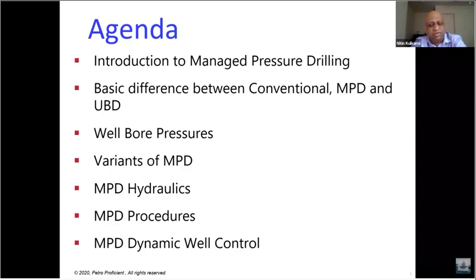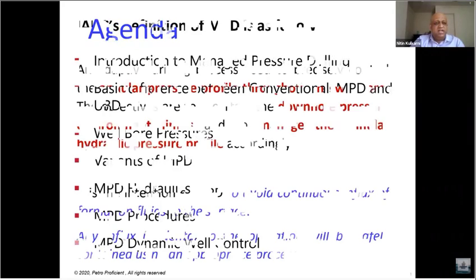dynamic well control procedure. Those who have been involved in the operations might be familiar with the fact that MPD as a tool can definitely enhance your well control capabilities. What it does exactly is what we will discuss in this last part, where we draw the line, because conventional well control is still what needs to be kept in mind and used in the event of a well control. But MPD can definitely aid in certain situations, and this is exactly what we will see. There are different tools that have been formed. We will review those. So let's get started.